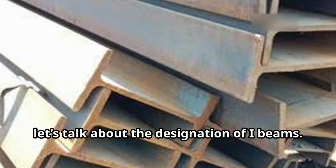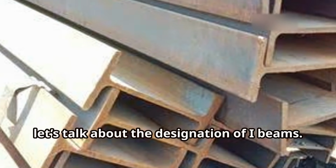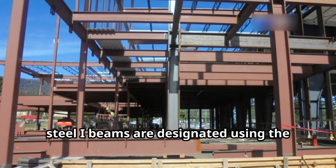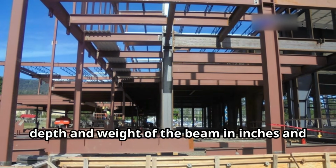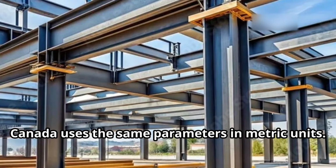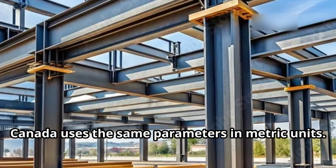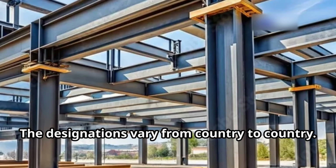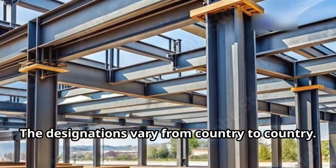Now, let's talk about the designation of I-beams. In the United States, steel I-beams are designated using the depth and weight of the beam in inches and pounds per foot, respectively. Canada uses the same parameters in metric units. The units are millimeters and kilograms per meter. The designations vary from country to country.